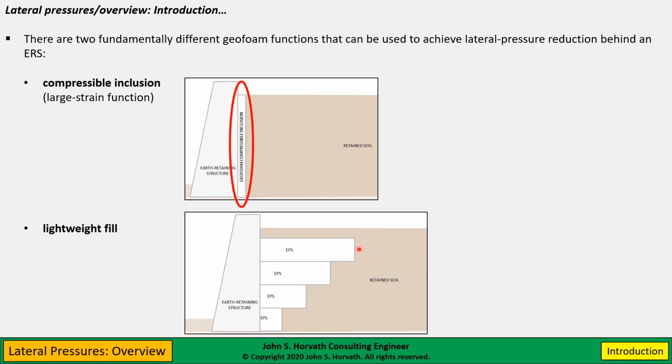This stair stepping is essential, and I emphasize that because if you look at some of the early magazine articles, for example, that talk about EPS geofoam, you will see that these blocks were placed with a vertical face. And we now recognize that that is not the way to go.